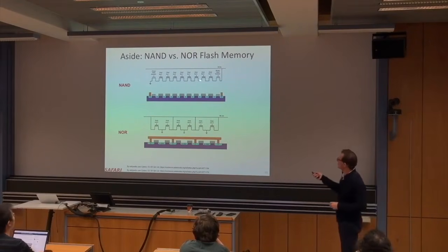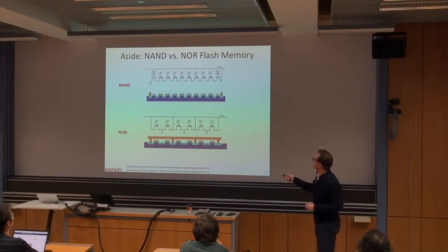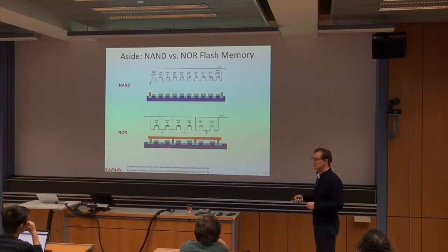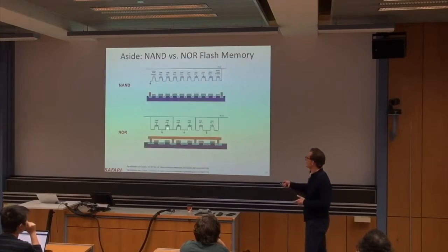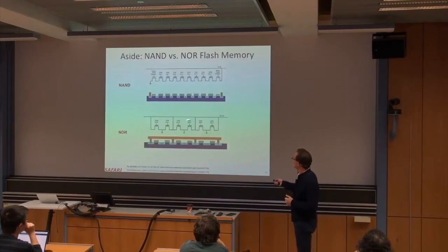As you can see, the density advantage, the bit line looks like this over here. Basically, this is the bit string that you have, and all of these transistors are connected to the bit line in a NAND fashion, which is what we actually looked at over here, which was NAND. Whereas here, it's like a NOR fashion. You can see that the bit line is like this, and the bit line turns on if any of these transistors actually turn on.